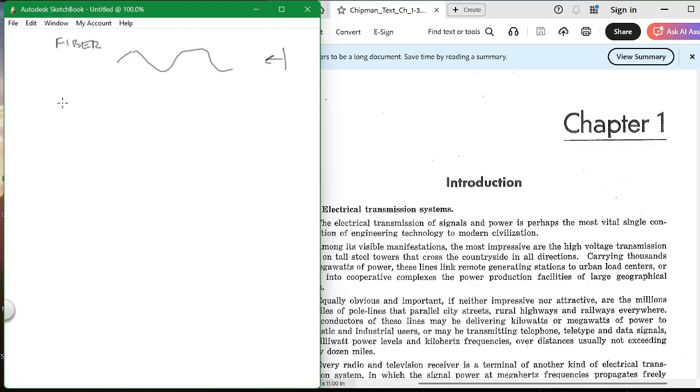So again, older cable techniques had to have some kind of a resistor at the end. You had to hang a resistor across the ends of your cable. So you would maybe run a cable from one room to another, and at the ends you would have to add a resistor of a certain value in order to blunt this reflectivity. And that's not true with the cables that we have today. With Ethernet cables, you don't have to worry about those end resistors. You did before, and those resistors had to be matched to the impedance of the line, or else it wouldn't work. So that resistor had to match the line resistance.